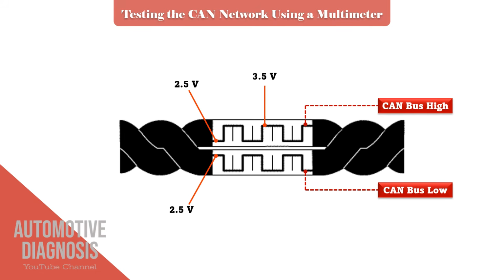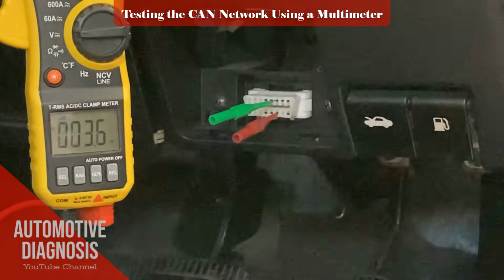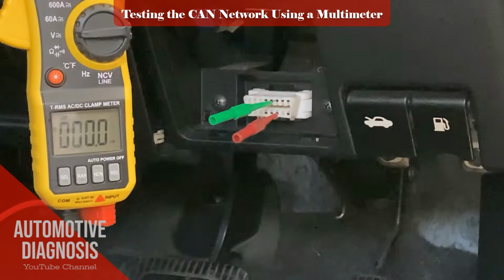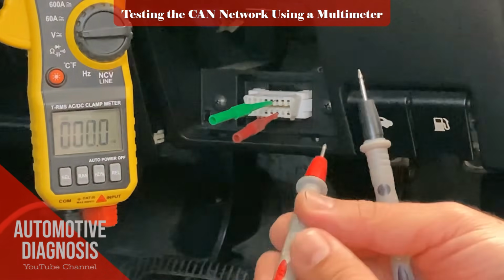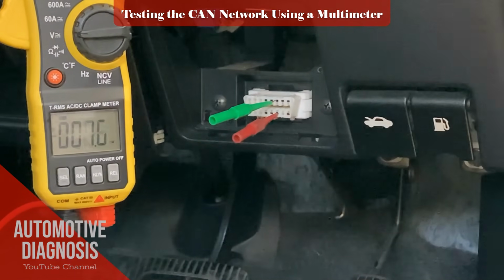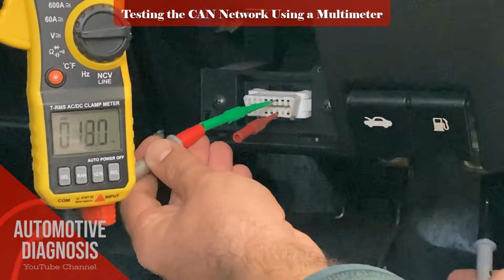This voltage change happens very fast, so if you are taking the measurement with the multimeter, you will read the average voltage, which is about 2.6 volt for the CAN high and about 2.4 volt for the CAN low. So for checking the voltage, I turn the ignition switch on to wake up the CAN bus. Then I check the voltage between the CAN high and body ground, then CAN low and body ground.